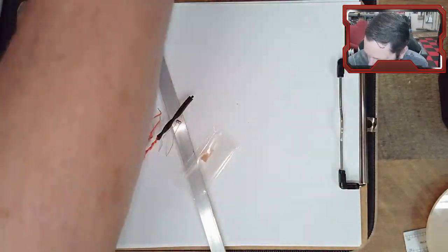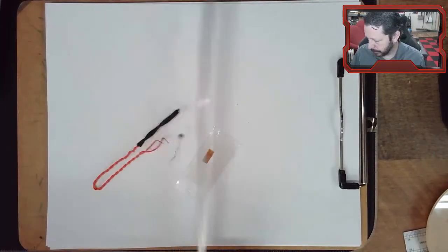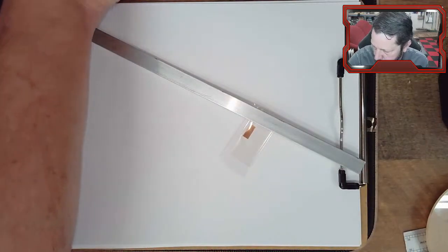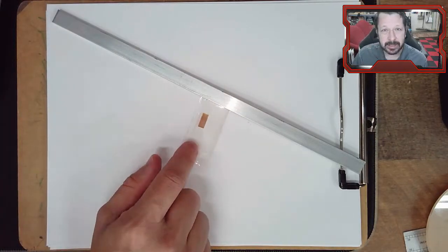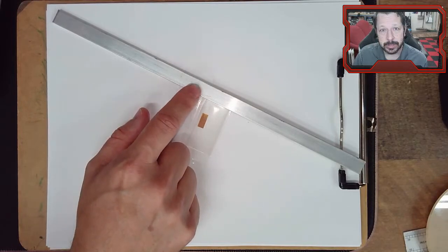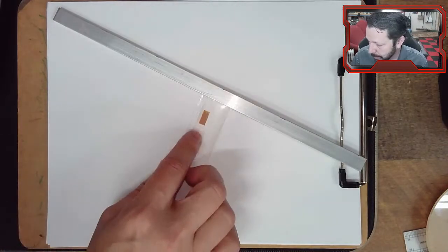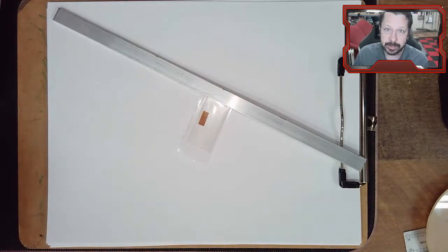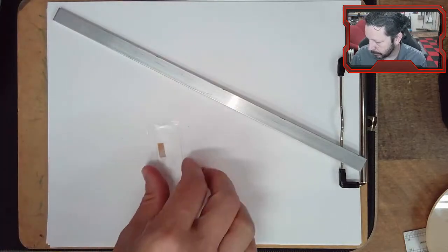We hopefully, we'll get to it today, are going to build our own little load cell out of a piece of aluminum strain gauge. We won't need these. Although I will say the thermistor might be helpful because these are sensitive to temperature changes also, because temperature can cause the base material to expand or contract. And so there will be strain induced just from temperature changes that are not related to the weight or the force it experiences. But we're going to ignore that for now.